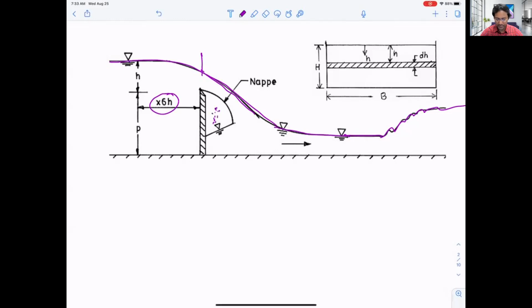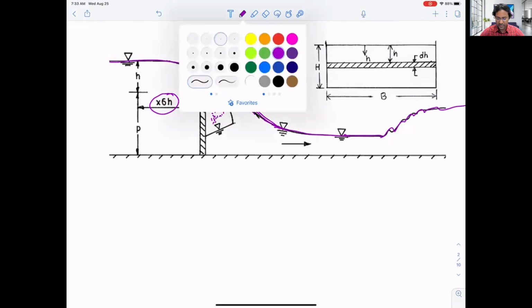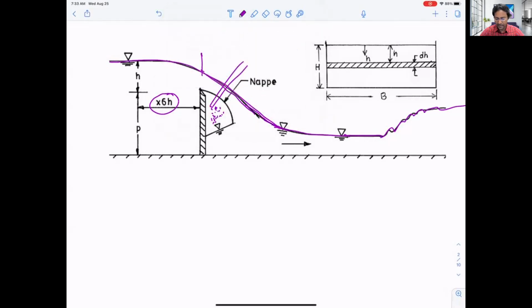So we have to make this space, we have to use one pipe to ventilate it. Once we ventilate this one, that will be atmospheric pressure, and we can see this is a free space. And then the water will fall on the surface on the downstream side of the channel, and then the flow will be supercritical. We know what subcritical, critical, and supercritical flow are.